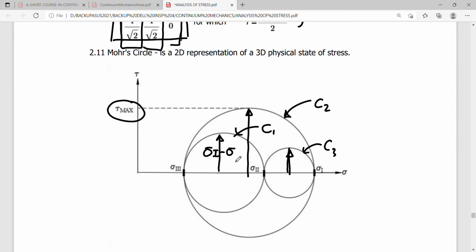Because we will be doing some graphical solutions later for us to visualize what the derived equations really are, as illustrated in the 2D representation of the Mohr circle. So this becomes now your sigma 1 minus sigma 2, of course, over 2 here, and this is the biggest radius, which is sigma 1 minus sigma 3 all over 2.